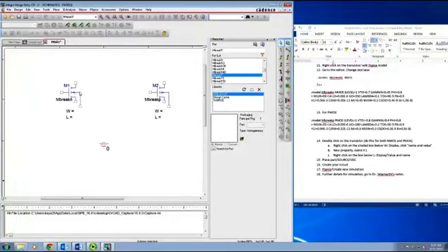Okay, now we have our NMOS transistor and PMOS transistor. We would like to do a simulation to get its IV characteristics. I will get rid of the PMOS from here for now, and I will just edit the NMOS transistor. So let's do first the ID-VGS. I need to put the source and the bulk to the ground.